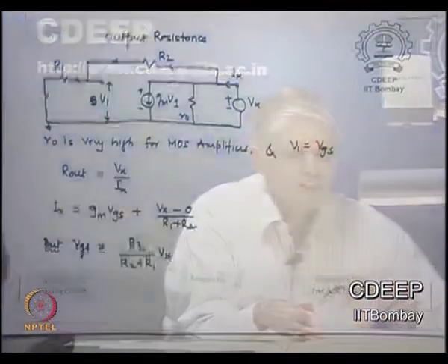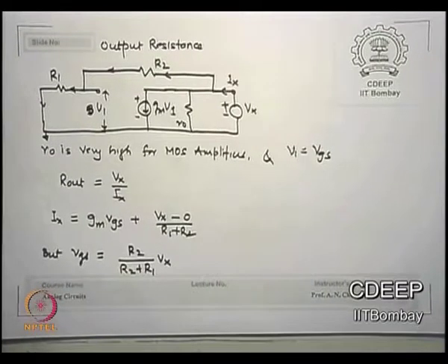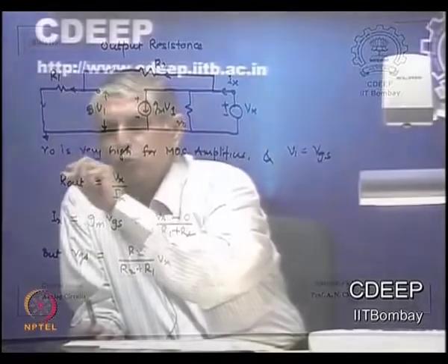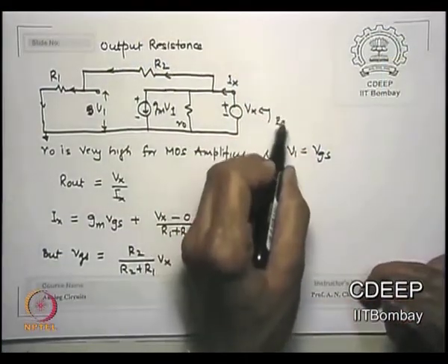Okay, here is another parameter of interest to us, the output resistance. What was said about how much the output resistance should be? It should be very small, you were saying, right? So let us see now. How do I calculate output resistance of a network? Short the input, at the output apply a voltage source, and the current starting from there, Vx by Ix, is the output resistance. This is my R out.